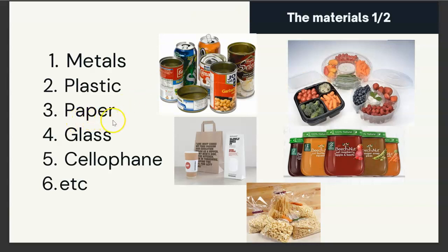The third one is paper and cardboard, like what is shown here. Of course, the advantages is generally they are biodegradable and very lightweight, recyclable, and renewable. However, generally they have poor moisture properties as well as poor grease resistance. Hence, it is less durable and can be more expensive to produce with enhanced properties.